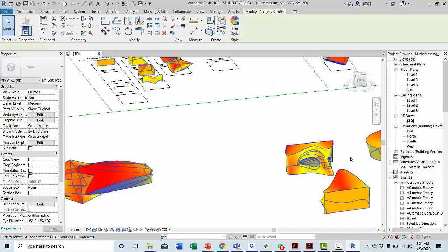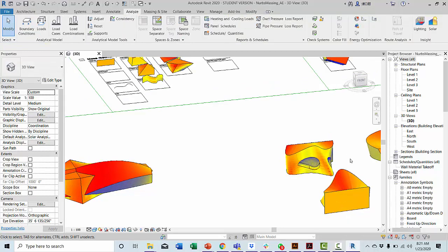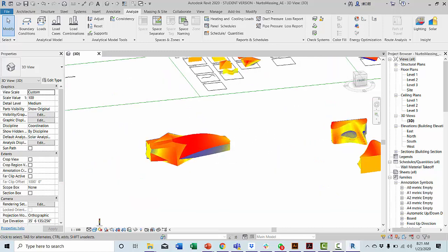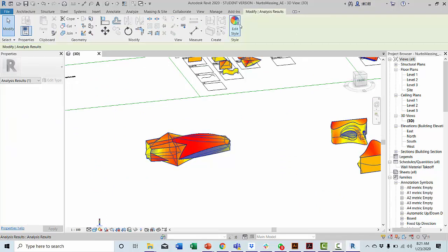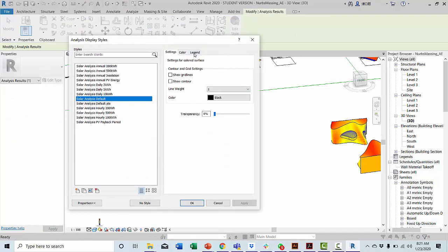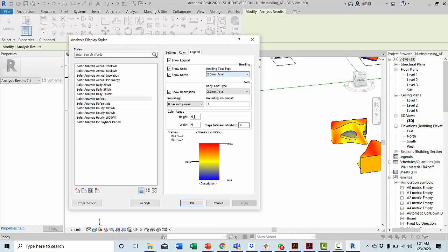So you guys are in design 9. Are you currently doing massing models for your site? Yeah. Not yet? Well, for the ones that are, and also whenever you finally get there, you can use these techniques that we went through with the massing and the NURBS modeling in Revit to quickly modify masses in order to run them through and start to get immediate feedback about what kind of conditions are going to be good for surface area to volume ratio, what's going to be good for solar analysis, and then how you can rotate or modify the form to get an optimal amount of sun exposure on areas such as, in this case, where you have blue, that's probably better to have a window, right?